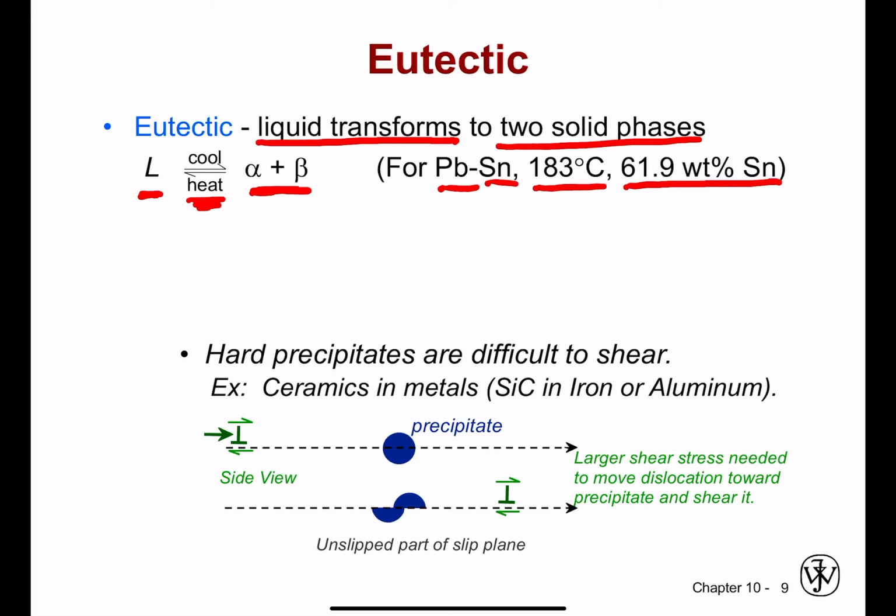Okay, and so typically the beta takes on the form of something like a precipitate, and so it'll provide things like ionic compounds or ceramics. And as we saw earlier in our work, these often act to prevent shear motion and plastic deformation, and so these are often used to harden a material.